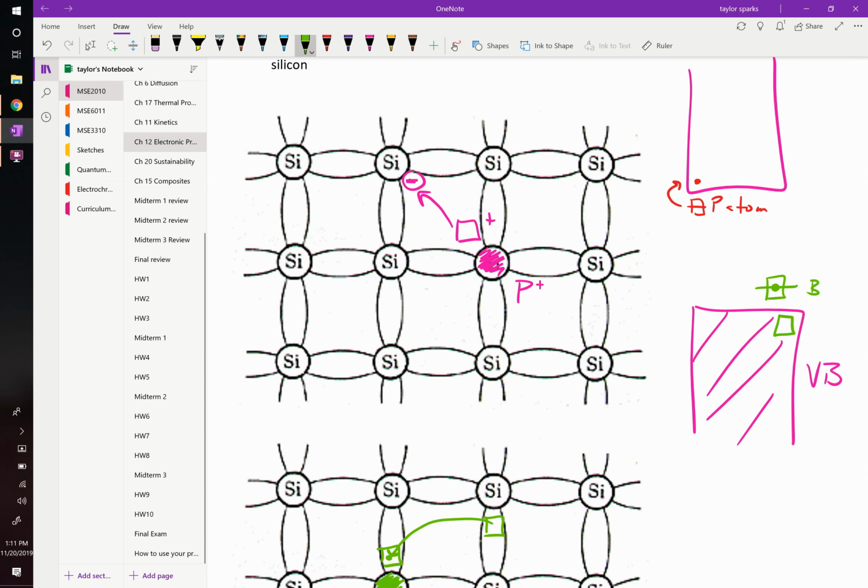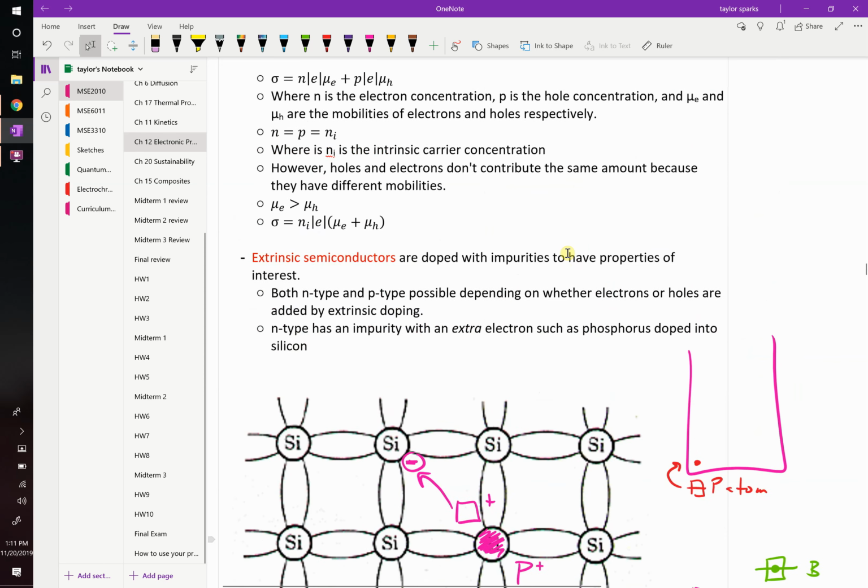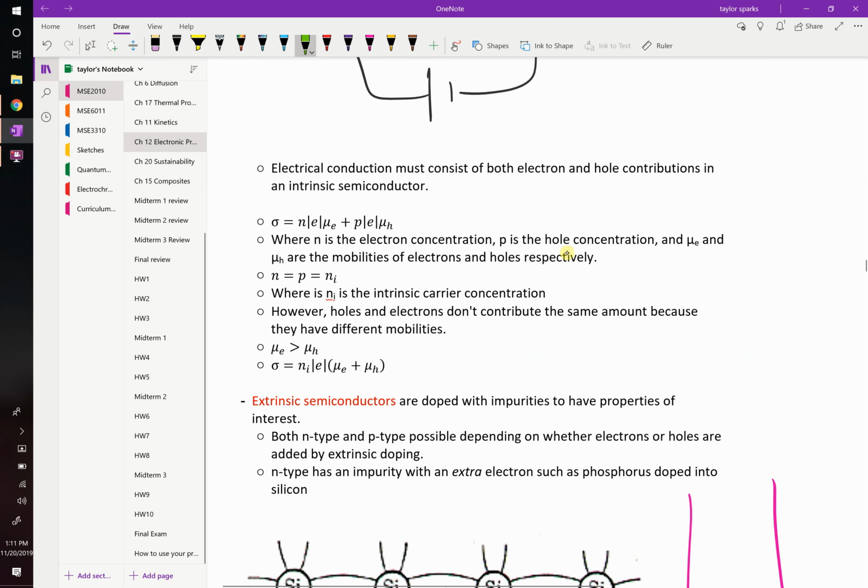And for the exact same reasons that we just described for phosphorus not being mobile, the boron atom is not particularly mobile. It can diffuse, but it's going to be slow, right? Meanwhile, this vacancy, the hole where an electron used to be, is much, much more mobile. You guys with me? So in n-type, we could basically cut out that term because the phosphorus atom is such a slow diffuser that we just don't include it. This is the opposite. We're going to be able to cut out that term, and it's only p, it's only holes that are moving in the material.